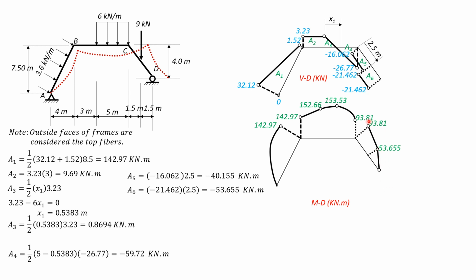So this is the moment diagram. And the elastic curve, so we have concave up somewhere here, concave up, and concave up. But these should be displaced to the right because that's a ruler. So all are concave upward elastic curve because the moments are all positive. So that's it for the solution to this problem.